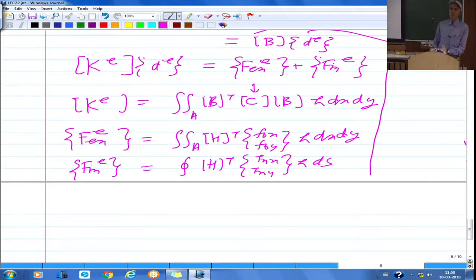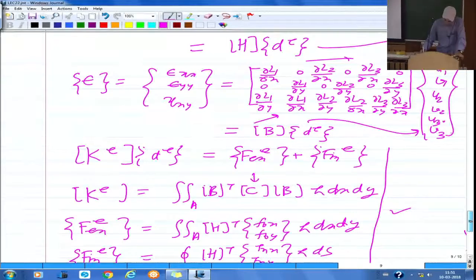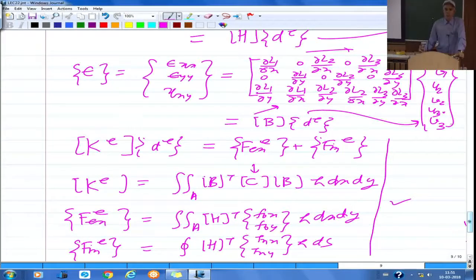So once you understand the problem, either the differential equation or the integral functional, you can decide what kind of element shape you want to choose, what approximation you want to choose, and then you can develop the element level governing equation in this fashion. Similar to what we did in the heat transfer problem, you can also take a simpler problem and try to solve it using this three-noded triangular element. And typically this element in solid mechanics, the three-noded triangular element, is also known as the constant strain triangle.